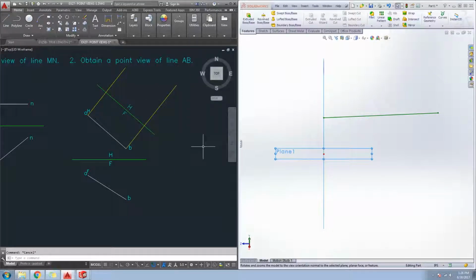There we go. So here's the view I want to make. One view back, two views back. So we're going to do our offsetting from here. I'm going to type offset command, point A to the folding line to A. Draw a little circle right there. That's point A. Repeat the process again. Offset, point B to here. Draw a circle. 1.